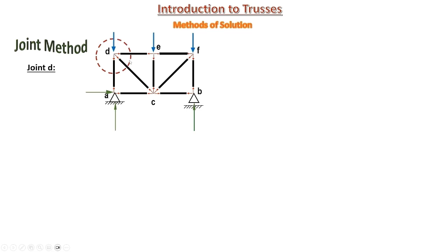In other words, we can observe any joint of the truss and conclude that all arrows of the internal forces are heading outside of this joint. This really indicates that all members connected to the joint were assumed to be tension members. Extracting joint D outside, we can analyze the force in DC into a horizontal and a vertical component.